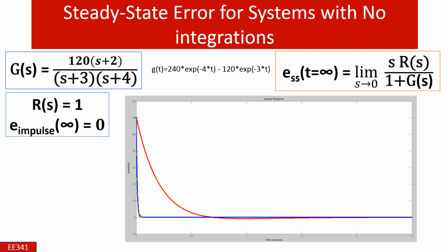For a type 0 system, for example, if we take the inverse Laplace transform of this one and try to plot it, we observe that the blue color is the input and red is the response, and this part is the transient part, and this transient part definitely varies accordingly, and ultimately the steady state result matches the input.